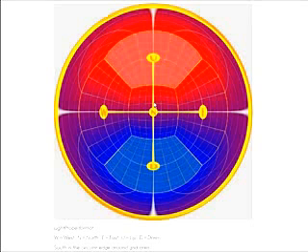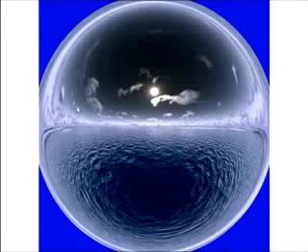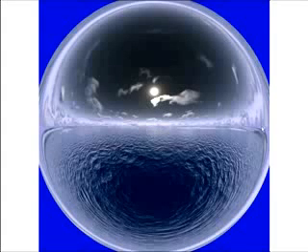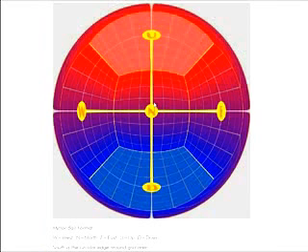The light probe is a 360-degree fisheye image, which really just means it shows a complete 360 environment, and it's heavily distorted around the edge of the circle. The center point of the circle shows the view forward or north, while the edge of the circle shows the view backwards or south. And editing this kind of HDRI is all but impossible because of the extreme distortion.